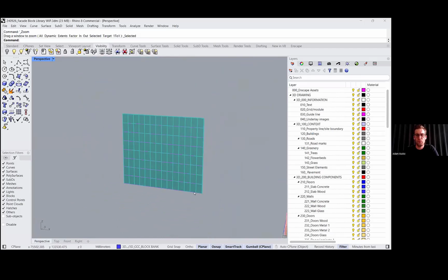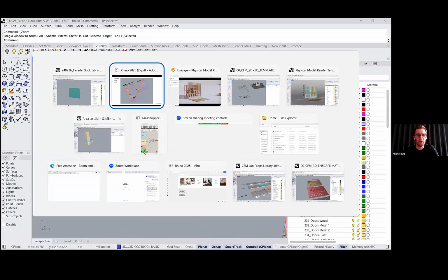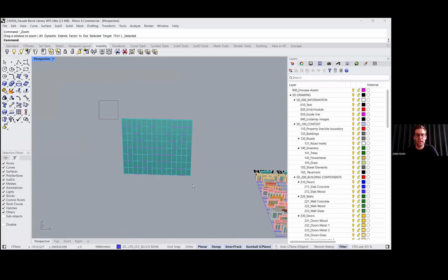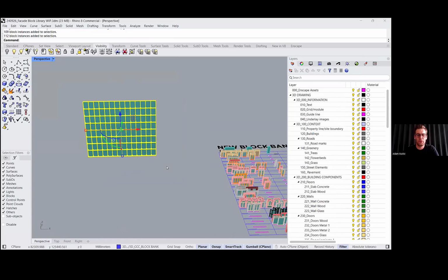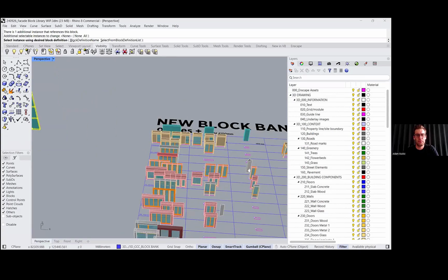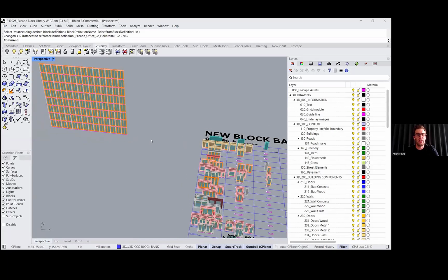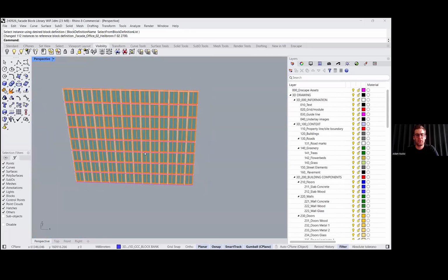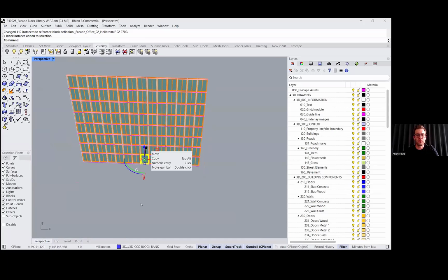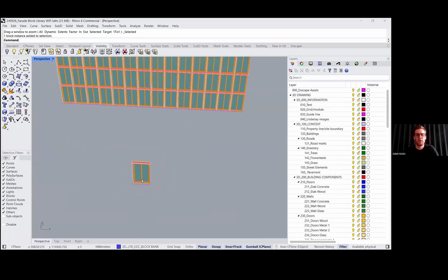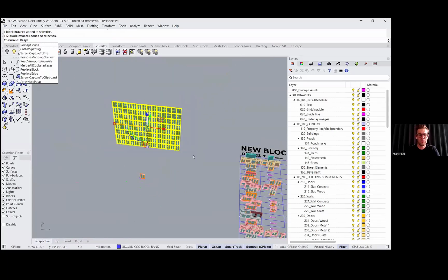So if we have a more complicated volume, something like this, first you just clad it with those tiles, and then we simply use the replace block command, and you pick a block of the same type and the same width, and then it's exchanged for something else. And then as you, for instance, study different types of it, what we do is we just make, maybe I'm gonna exchange it again for something that's more symmetrical.